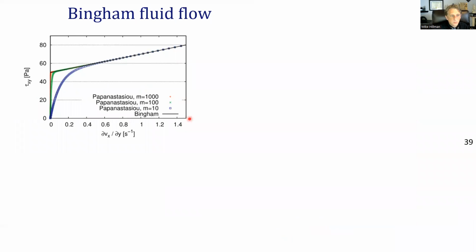Turns out this is a viscoplastic fluid, or it's actually not really fluid or solid. It's got rheological properties. So a popular model is the Bingham fluid, which has a yield stress, and then it'll flow in a non-Newtonian manner after that yield stress. And it turns out that you have to use regularized models, right? You have a kind of step function here, which causes some numerical problems. So you actually have to use